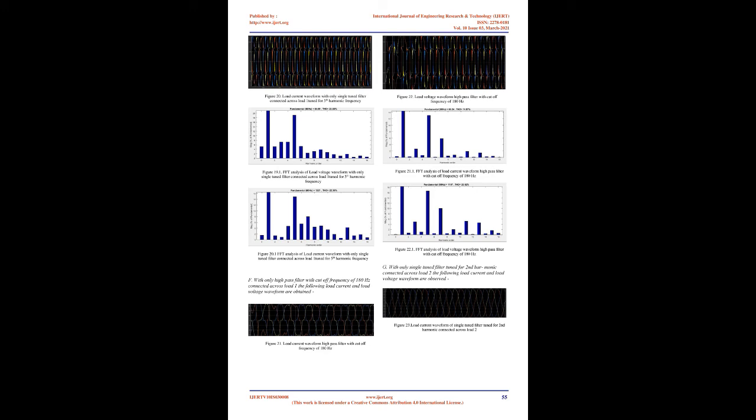The PV array block menu allows you to plot the IV and PV characteristics for one module and for the whole array. The PV array block has two inputs that allow you to vary sun irradiance, input 1 in W/m2, and temperature, input 2 in degrees C. The irradiance and temperature profiles are defined by a signal builder block which is connected to the PV array inputs.